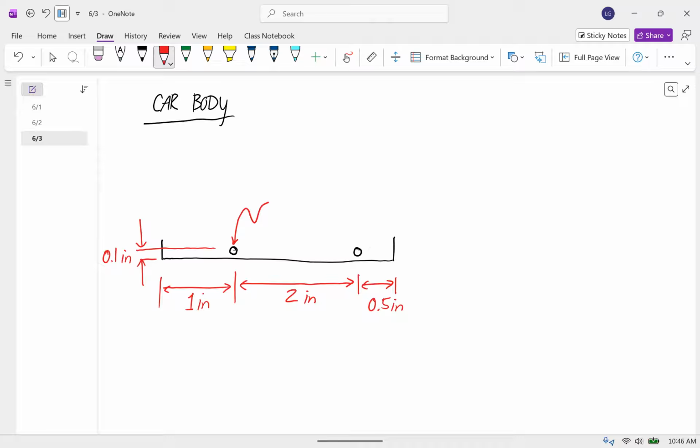And so that's about 0.04 inches. So we're going to make a clearance of 1 millimeter for this hole. Anytime you 3D print something, if you don't leave a clearance of right around a millimeter, it's not going to move. Things are going to catch on little imperfections and things.